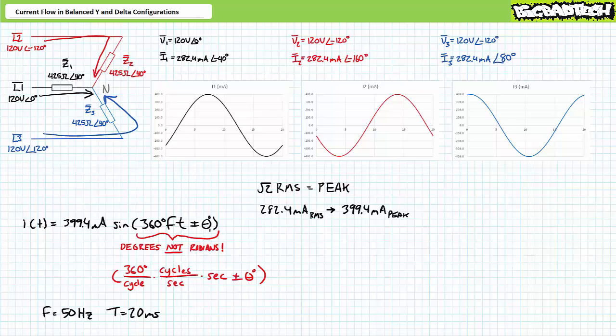However, the period for a 60 Hz waveform is a rather ugly 16.7 milliseconds that doesn't evenly divide for the purposes of instantaneous step-by-step analysis. A 50 Hz waveform, however, is a cleaner 20 millisecond period that we can seamlessly divide into any degree of fineness we choose. For the purpose of this exercise, let's do 10 separate analyses in 2 millisecond increments. I'll demonstrate the procedure for the first couple, and then just let a computer do the dirty work.